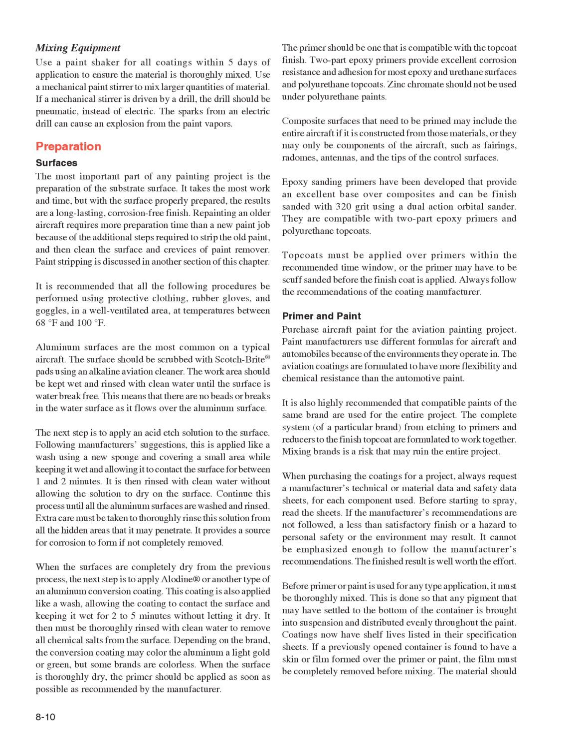The next step is to apply an acid etch solution to the surface. Following manufacturer's suggestions, this is applied like a wash using a new sponge and covering a small area while keeping it wet and allowing it to contact the surface for between 1 and 2 minutes. It is then rinsed with clean water without allowing the solution to dry on the surface.